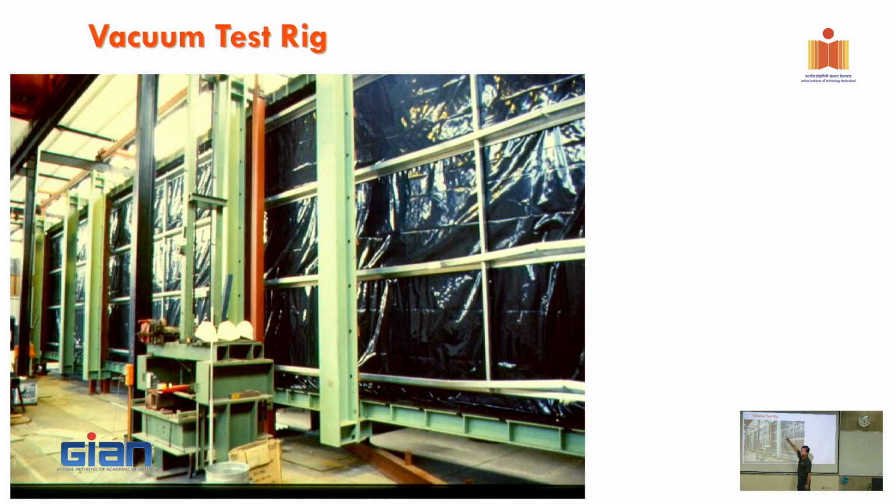So showing you, this is the vacuum test, a huge vacuum test. Everyone knows that when we want to test a roofing system, we have to build a vacuum test, right? And we suck the air, similar to how it works in practice where the roof is subject to wind load or other load. So you can see that huge vacuum test. The height here is about 5 meters. So that is the roof where we put it vertically. And there are 3 spans, and each span is 7 meters. So the length here is 20 meters, and 5 meters high.